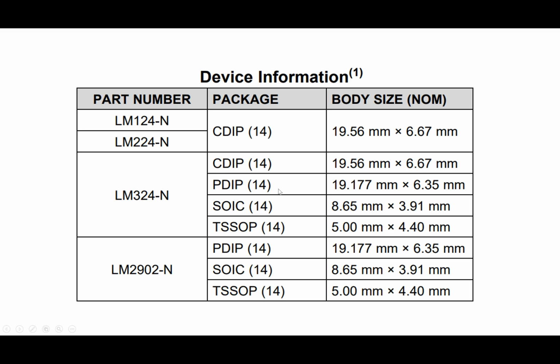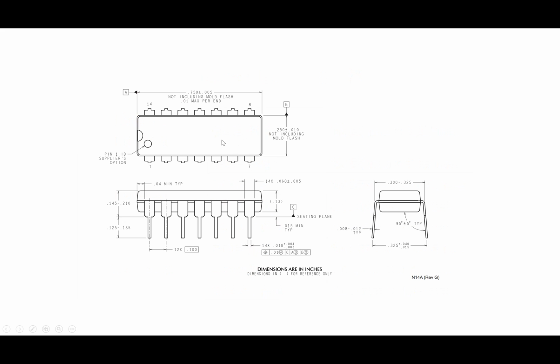So typically in the data sheet, what I find if I go later into the data sheet, here I have mechanical information that tells me about the footprint of the device, right? We'll need this information. We'll be looking at this information to make sure that we align and have our holes.